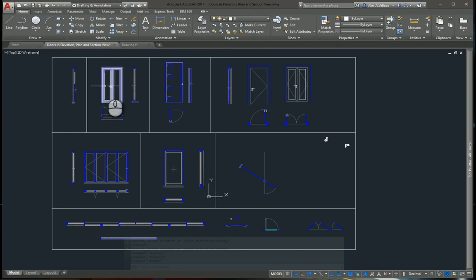So you will understand what it means, but AutoCAD will understand they are 2 different things. Okay, so you can do that. If you do the same name, it won't work. Whenever you try to import some different drawing, it won't work. You can try, it won't work.